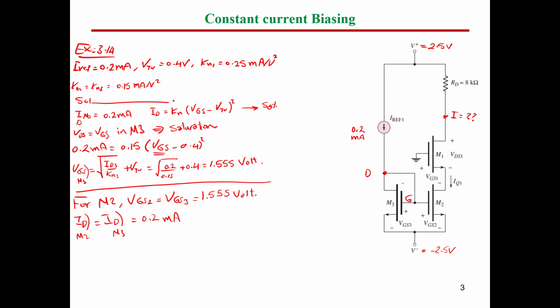Take care, guys. We discussed this many times. The drain current flows here and the gate current equals 0 in a steady state. So all of the time we consider that at steady state the gate current equals 0. This doesn't mean that the MOSFET does not absorb current to start.